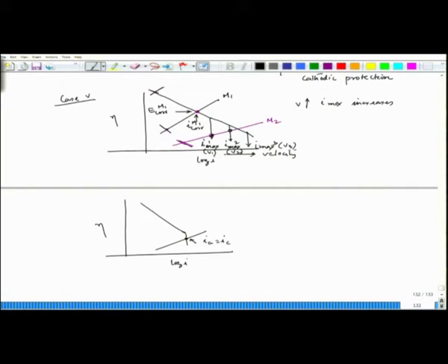Now, if we increase the velocity, the new mixed potential is at this point where again IA equal to IC. Now, if you increase velocity further at this particular V3, I could see that it is not cutting in that concentration polarization region. I am cutting the cathodic polarization line at this point where again IC equal to IA, and IA is nothing but the corrosion rate. So, let us say I plot corrosion rate.